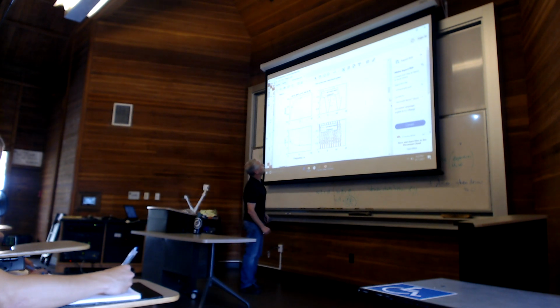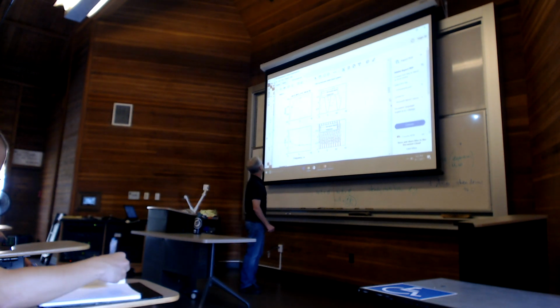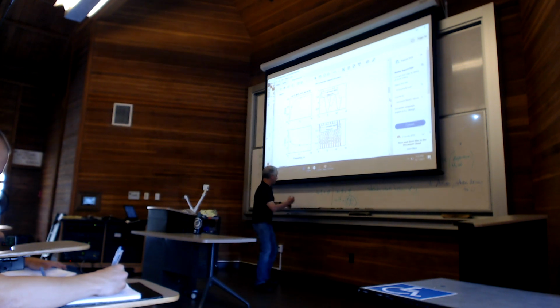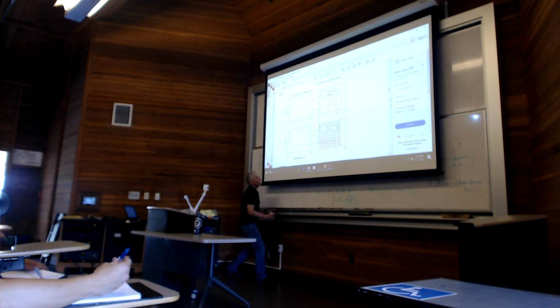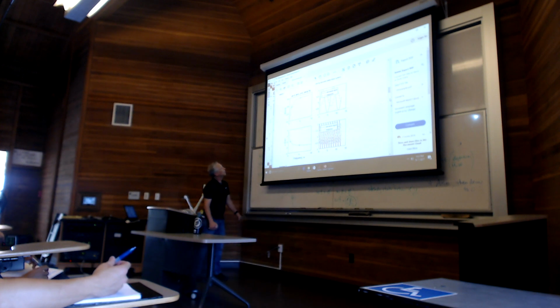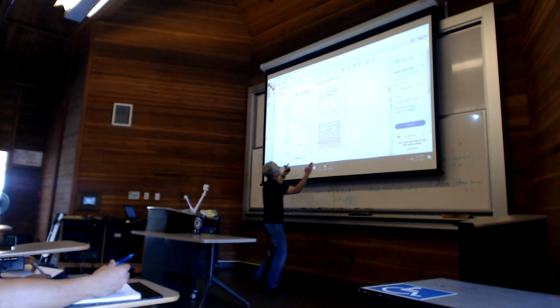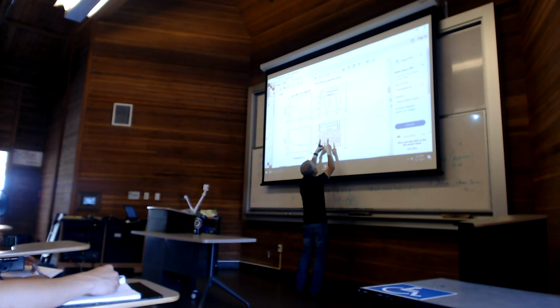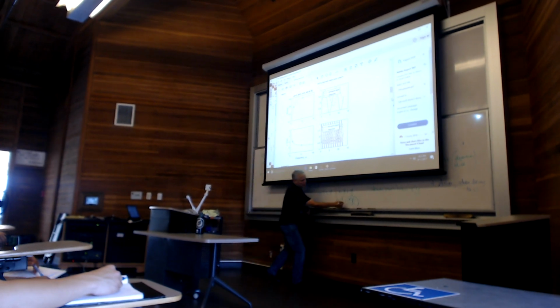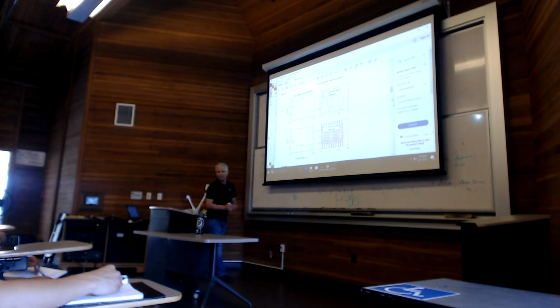And let's see what's happening here. Yep, and so that's happening, right? The red is the forcing function. And look what's happening when it finally settles in. The dotted one is about 1/3 of a period behind. We can kind of eyeball what the period is. It's about that distance from 4 to 9, about 6. And sure enough, that's about 2 units behind. So it is about 1/3 of a period behind, which is what we expected. Does everybody understand that? So that's consistent.